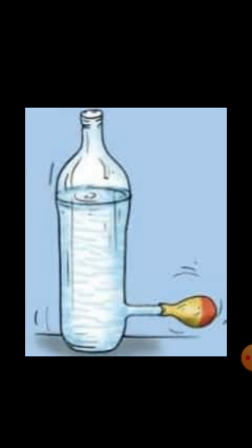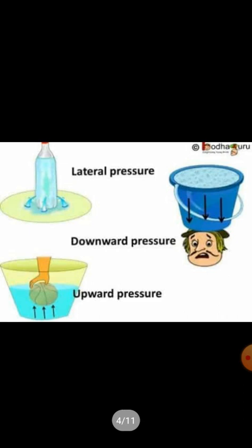Pressure exerted by the liquid sideways on the walls of the container is known as lateral pressure. Also, the balloon bulges more on adding water because when the water column increases, the pressure increases. Lateral pressure increases with depth. Not only downward pressure and lateral pressure, liquids also exert upward pressure.